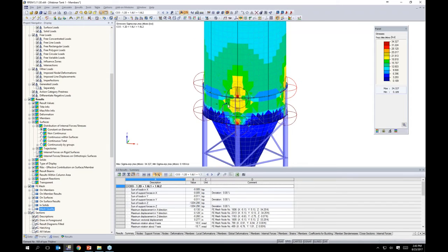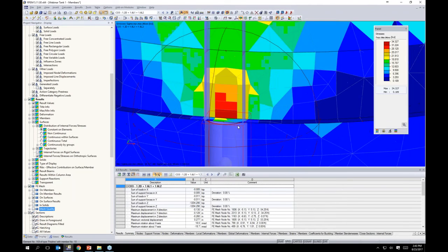So now you'll notice things don't really flow together quite nicely, but what's happening if I zoom in is that each FE element has its own value. Then we're basing the contour colors on each individual FE element rather than trying to average them all together with the smoothing algorithm. You'll take notice too that my stress went down from 58 KSI now down to 34. So you can see how this is incredibly important for how you're viewing your results. You may be over designing something if you're not viewing it correctly within any finite element software.